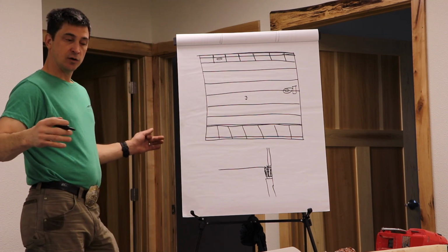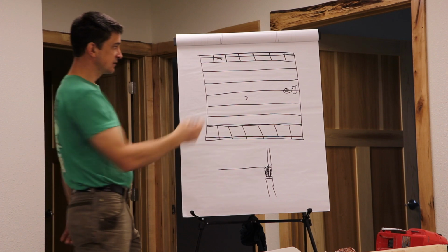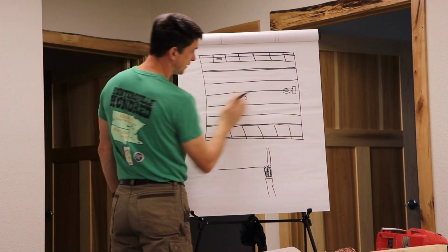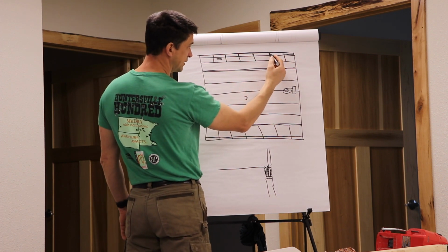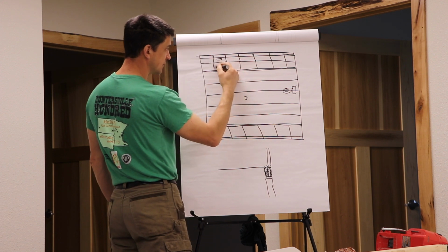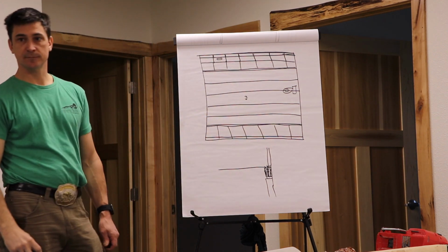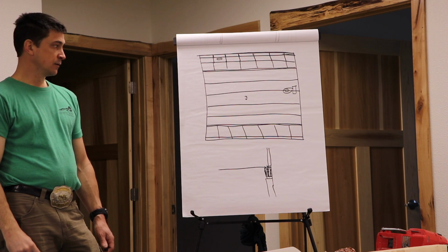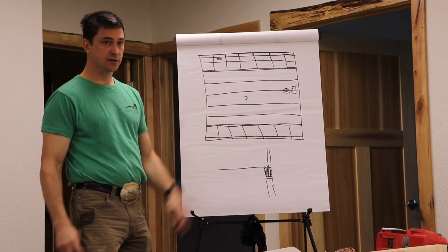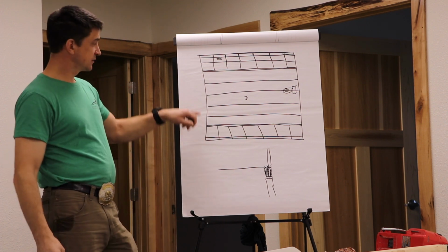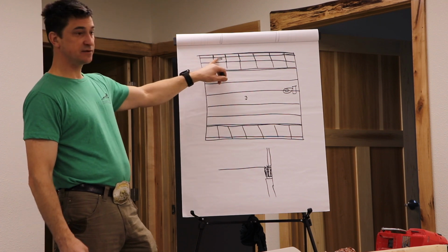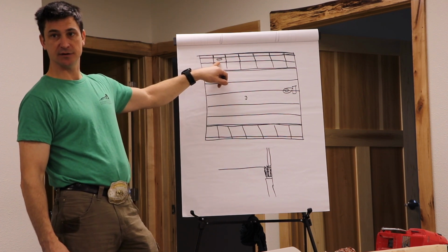And so another option for this is to not even put this one in here, to double this one, and instead of running a 14-inch block in here, run a 30-inch block. Because then it's really easy. Then, all the way around, it's like these end joist cavities. You guys know from insulating, you have awesome access to the rim joists here. These ends are a royal pain sometimes, aren't they?